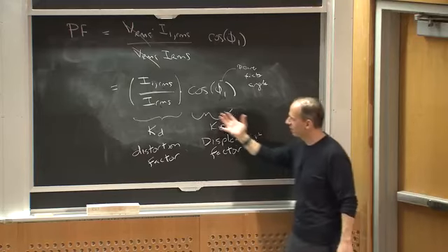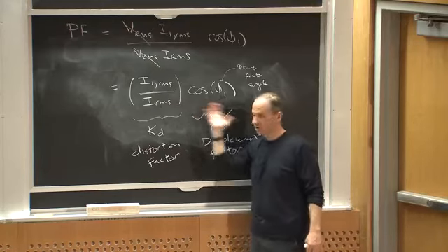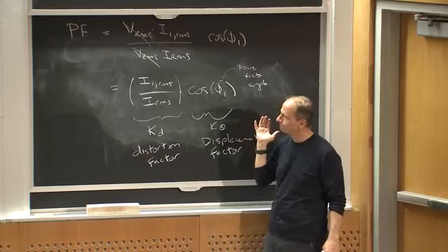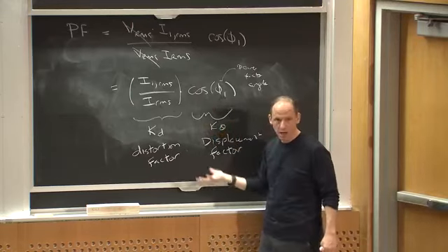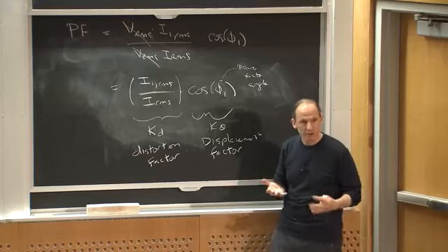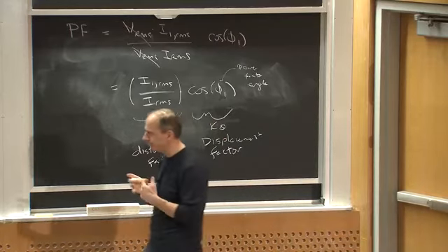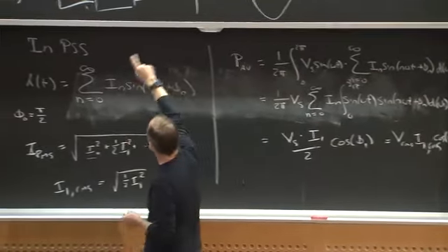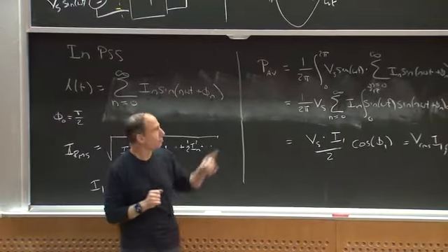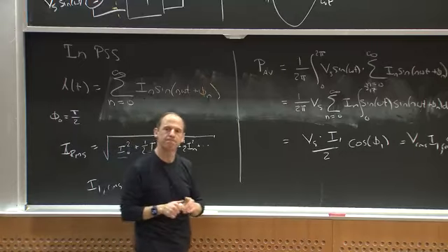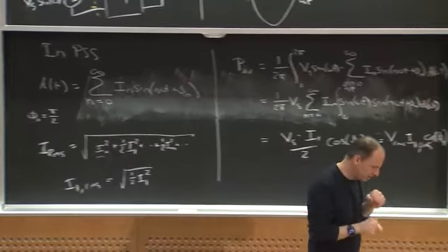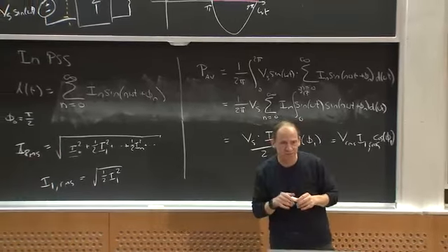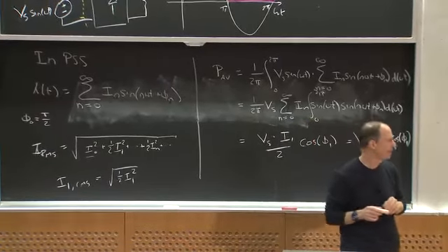Okay? So this is a very useful way sometimes to decompose what's going on, because if I really cared about the power factor, I might need to know that. And you say, well, why is that true? Because suppose I connected up a rectifier like this, drawing the square wave current. Okay? First of all, this would be horrible because it has a DC value, which a lot of transformers don't like. But suppose I put that aside.